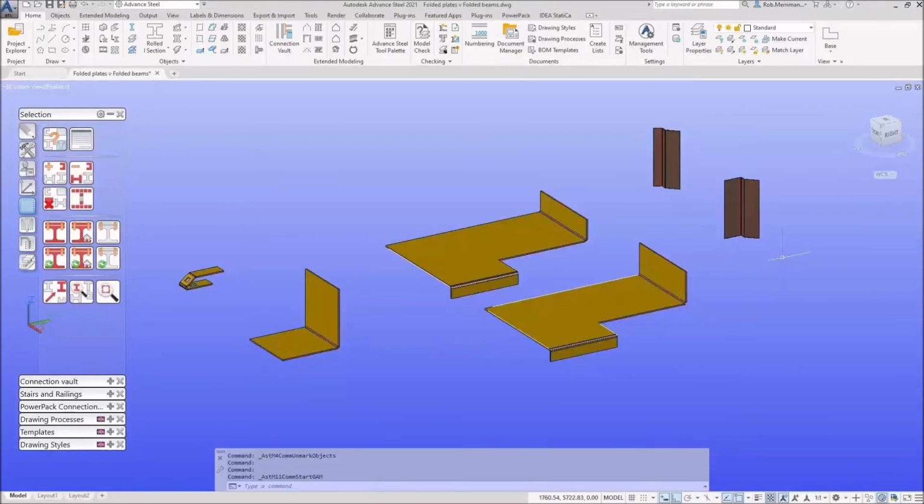I think when me and Alec discussed this, we even have different ways of doing it. I've always done anything that is a standalone item or a loose piece as only an assembly drawing, because I want that to go into an assembly drawing that gives you the coating, and it tells a workshop that this is a finished item. Even though there's nothing welded to it, it is a finished item. So you cut it, you fold it, you crop it, you punch holes in it, and then it needs to go for finishing. Alec prefers to do it as a single part, because he says, well, it's a standalone item, it is a single part, so he puts it on a single part drawing.